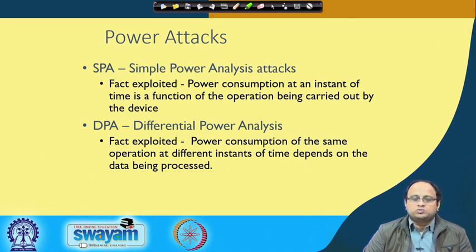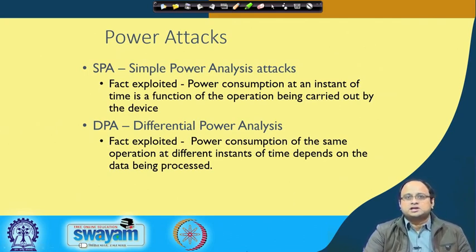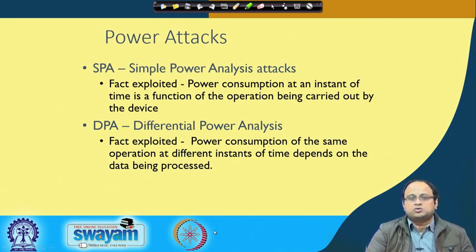So you would get an idea about what your multiplier, squaring, doubling or addition is operating on. If you have an idea about the intermediate data, you can follow it up by cryptanalysis to get the actual secret key. DPA is a very powerful attack model, and as we will see in more detail in our class, it can lead to very efficient attacks against implementations.